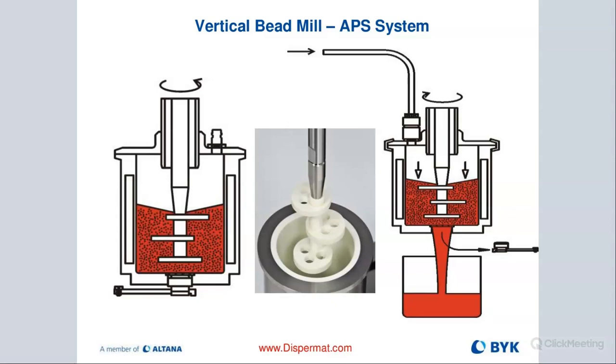This is more for a lab space, not really for large-scale manufacturing. We can go up to about 35 liters of slurry with this system. We basically have two containers, a top container and a bottom container. On the top container, we have our slurry. If we want to mill, we just add beads, replace the cow's blade with the milling disc, and then we are milling. You can see on the bottom of that container there is a screen and a drain plug. When we are ready to purge our slurry, we plug an air hose into our cover and pressurize our chamber and force the slurry out of the container into the catch pan or another container below. That will be our milled material.